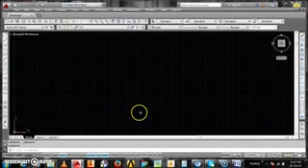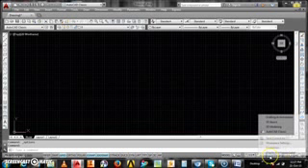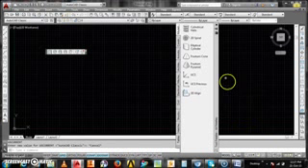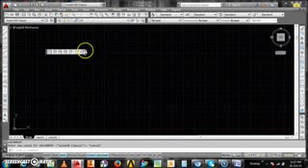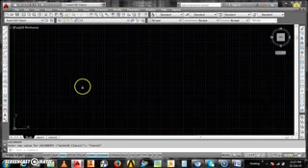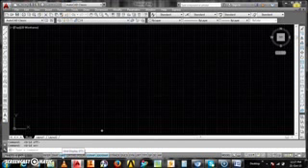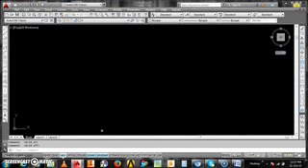Now the first thing in AutoCAD is you have to go to settings and click on AutoCAD Classic. Close this, close this. Now I don't want this grid, these square shapes, right now, so I will switch it off. You can click on Grid to switch it off, or else you can press F7. If you press F7, you will see the grid is no longer present.